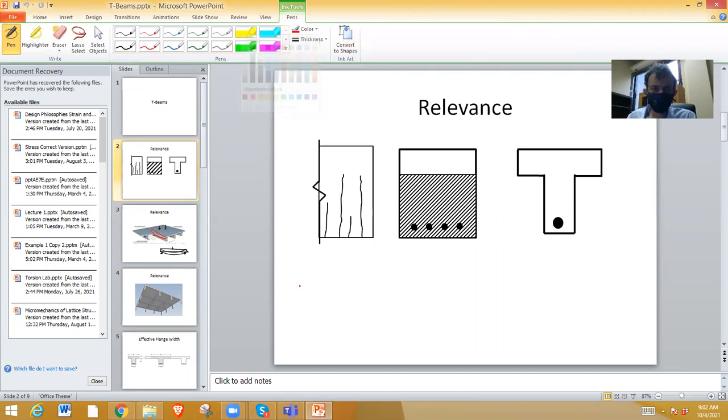as compared to a rectangular section, in a rectangular concrete section, we know that concrete is not carrying any tension. Only the compression part is useful, and then the tension is all carried by the steel. So it makes sense that this T shape, where you get rid of all of this, is better than the rectangular shape. So this is one point.